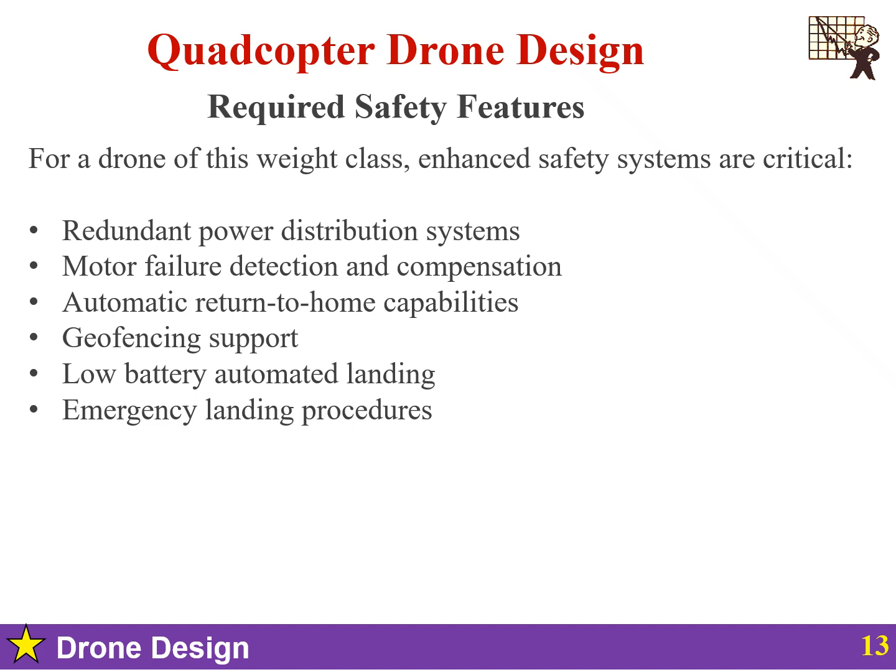Some additional professional systems include redundant flight controller, dual flight controller architecture with independent sensor systems, automatic failover capability, and cross-checking for fault detection. The next is parachute recovery system. For catastrophic failures, ballistic deployment for rapid activation, sizing that is descent rate less than 5 meters per second for 7 kg total weight, automatic deployment triggers, free fall detection, altitude loss.